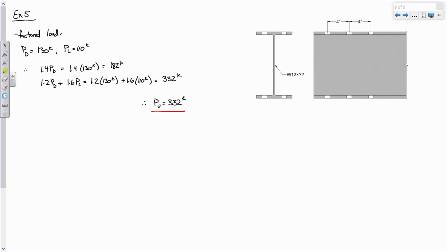It's all about the mechanics. I will go ahead and tell you that for tension members and for members that are loaded axially, you can, at least for the most part, ignore that for the purposes of design. If you have a really, really heavy column, you probably need to consider it. But for design purposes, for tension members and compression members, you can largely ignore it. Beams, however, that's another story. Members being bent tend to be weaker flexurally than they are axially. So as a result, you do need to account for self-weight.